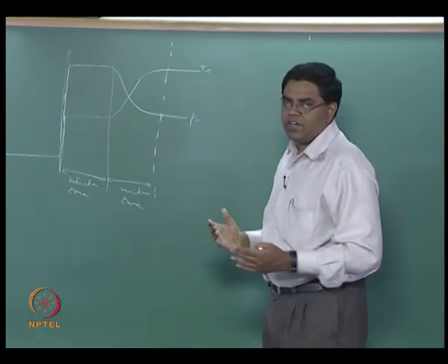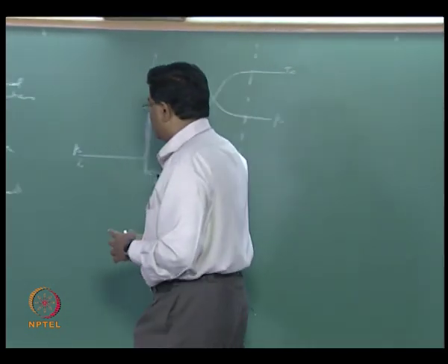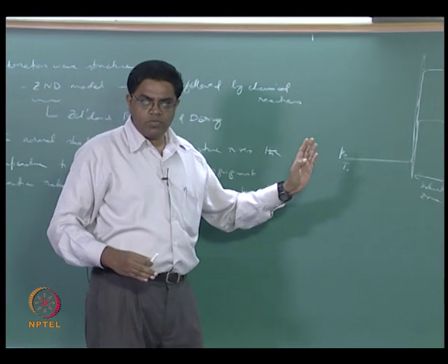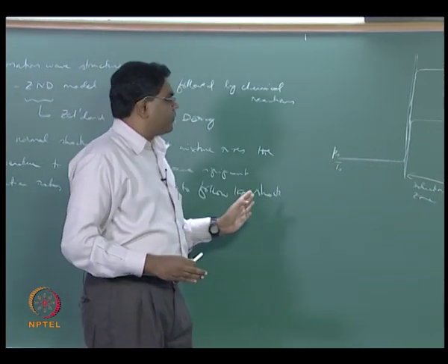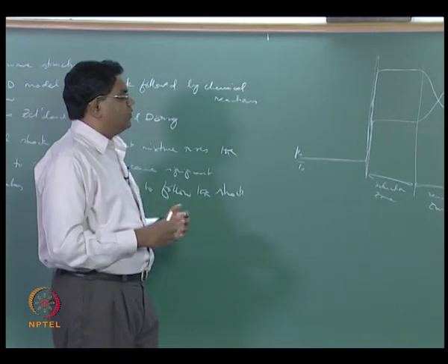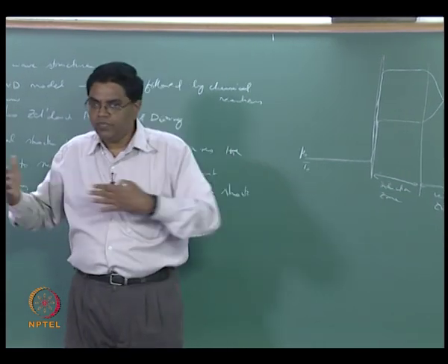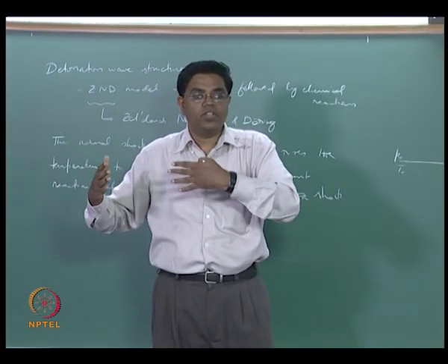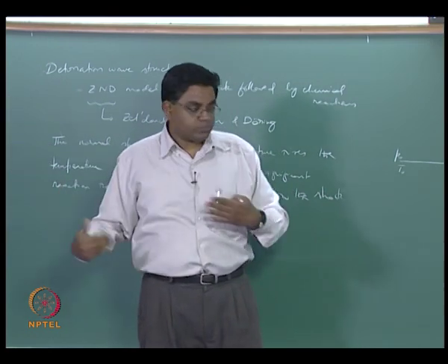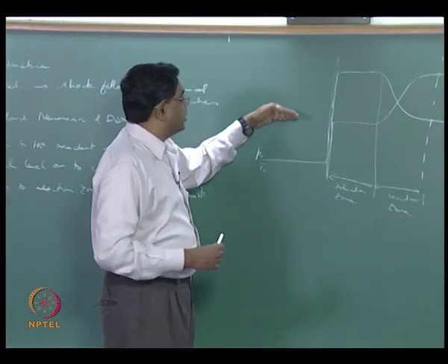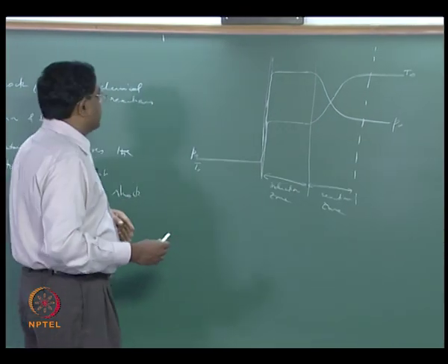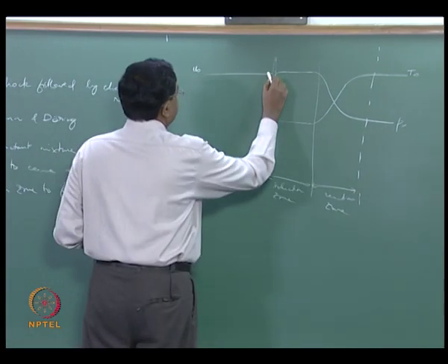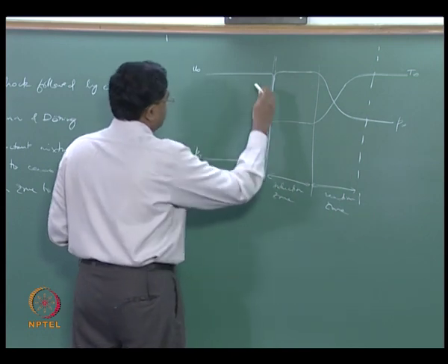Similarly, can we now think about the velocity, right? Across a normal shock the velocity decreases, and we are talking about a Chapman-Jouguet detonation wave for the most part. In any case, in all these detonations we found that the products follow the wave at a velocity, or at a Mach number, that is lower than the incoming Mach number, right? So you have to end up with a lower velocity than you start out with. That means you start with a high velocity, that's your u0, and then this decreases significantly across the shock.